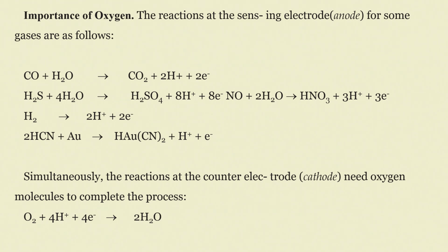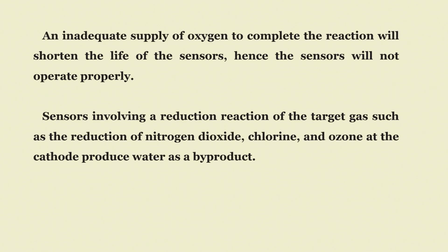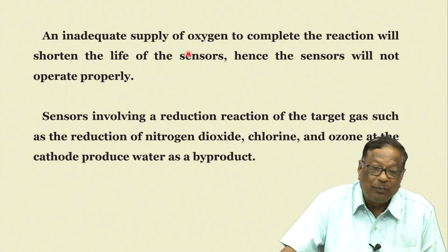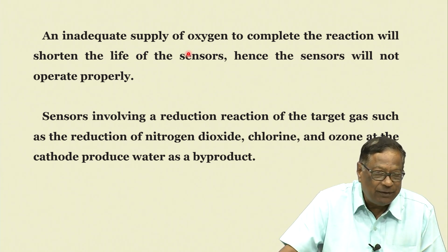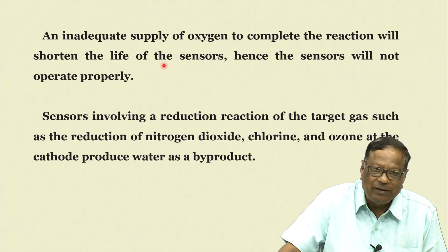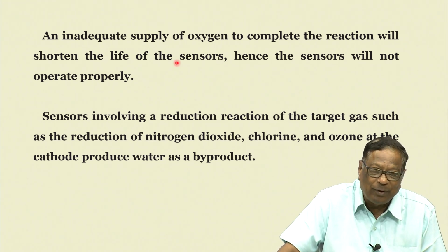So, in all sensors, water is the enemy. The enemy for all electrochemical sensors is water. An inadequate supply of oxygen means the reaction will shorten, and the life of the sensor is gone. So, the sensors will not be operating properly. If there is oxygen and there is water, then all the other reactions that I had shown in the previous slide will start operating and we will have problems here.